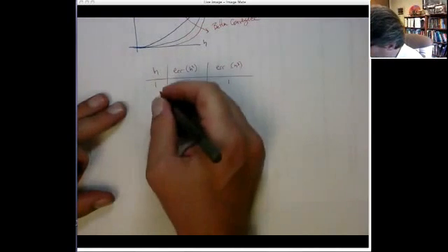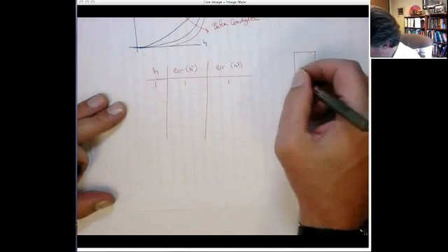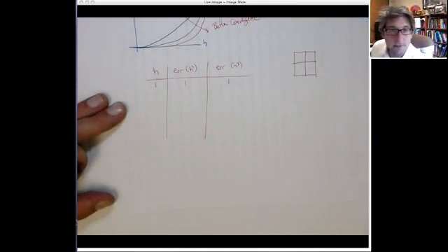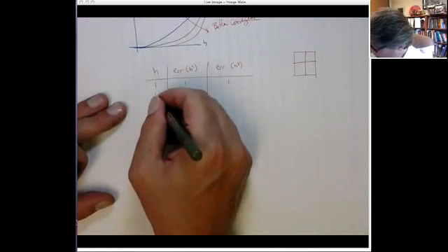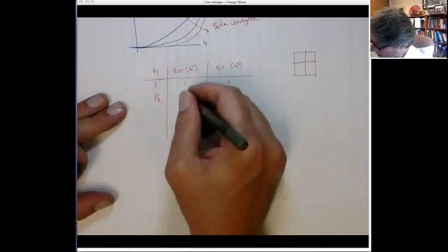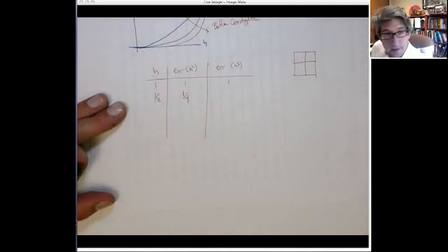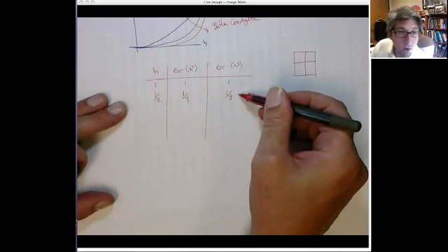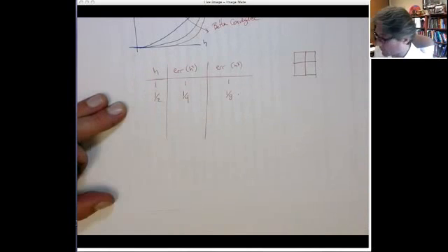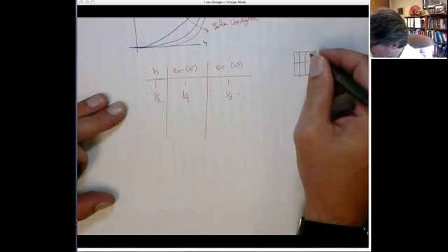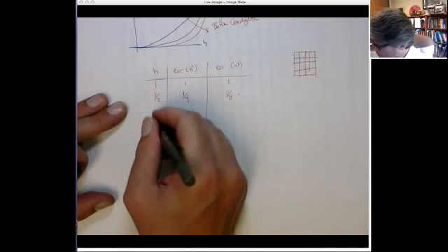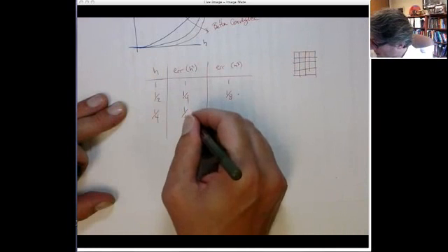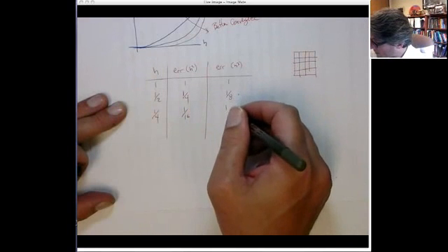Now if I take the element size, so this, let's say, corresponds to an element like this, and now we halve the element size. So h has gone to a half, all right? This becomes a quarter, and this becomes an eighth. So already the error started to drop more quickly with the cubic convergence than the quadratic convergence. And now if we take the element size again and halve it, this becomes 1/4. This becomes 1/16, and 4 to the third is 16.